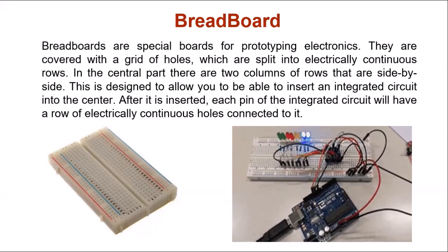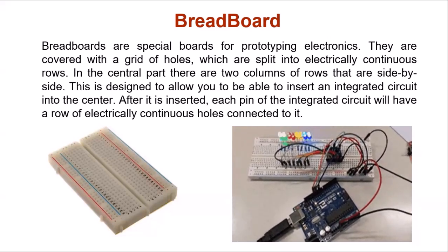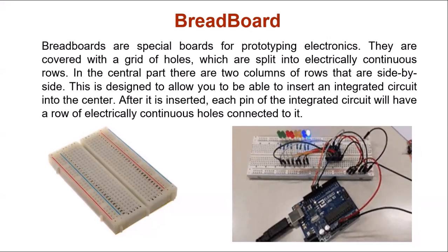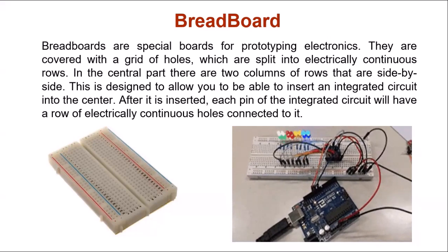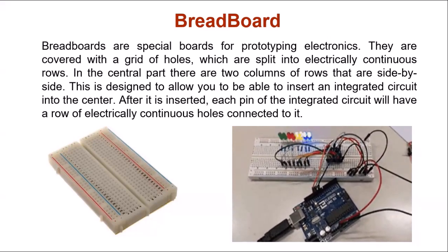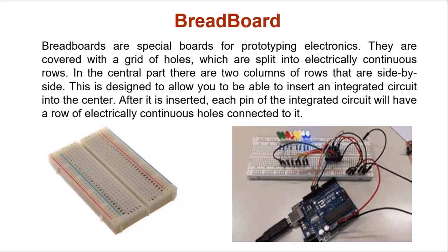Okay, so let's talk about the breadboard. Breadboards are special boards for prototyping electronics. Prototyping means making the circuit for testing purposes. When you are making a basic circuit and need to test it, you can use the breadboard. They are covered with a grid of holes which are split into electrically continuous rows. In the central part, there are two columns of rows that are side by side. This is designed to allow you to insert integrated circuits into the center.